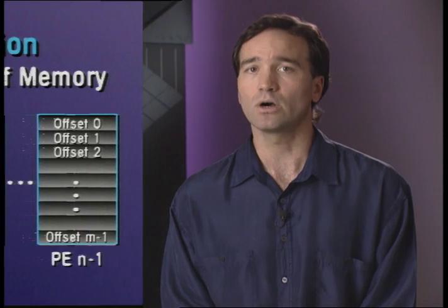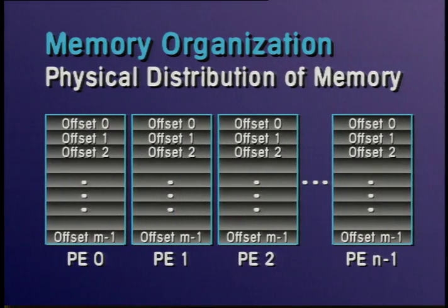Several additional address bits are also needed to control caching and to facilitate control of the memory map mechanisms that implement the external MPP shell. So, an external address extension mechanism of some sort is required. In T3D, this takes the form of a 32-entry register set called the DTB annex. The way memory is distributed in T3D, addresses have two parts: a PE number part that says essentially which bank of memory, and an offset part that says which memory location within the bank.